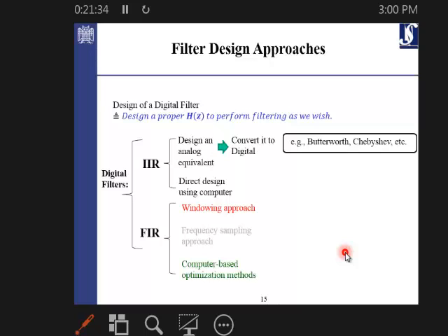There's no way to get an FIR filter for that. The impulse response always goes to infinity. That's why, for example, if you use an anti-aliasing filter, it should be devised in analog form, and definitely this response will be IIR.